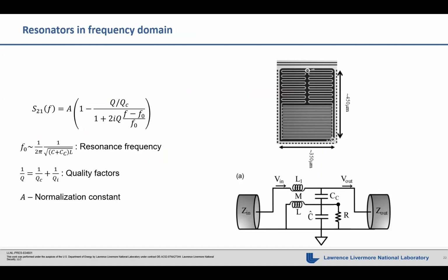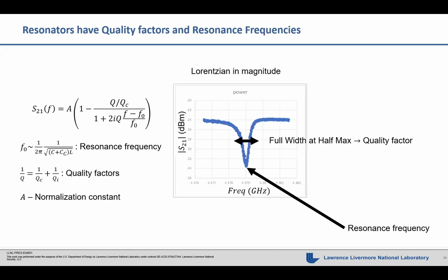So we can write down a circuit, a simple LC circuit. We add a resistor because all circuits have to have resistors, and then we have to couple to the outside world. We either couple capacitively or inductively. This is one of the simpler ways of representing one of these circuits. We have the frequency for that system. It's 1/√LC. It has quality factors, and we can write down a simple equation of motion for it.